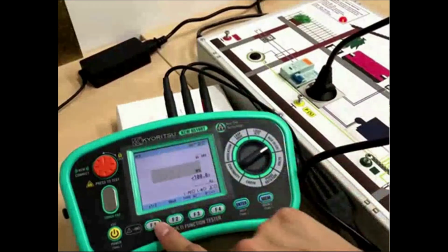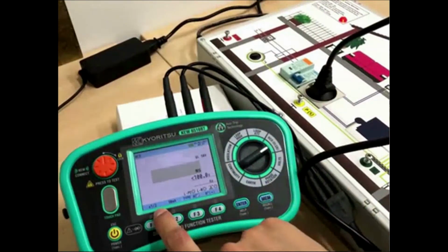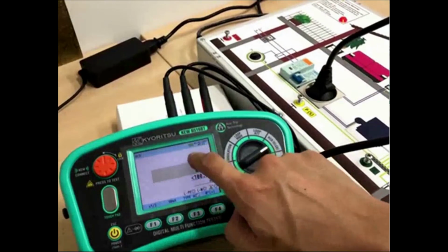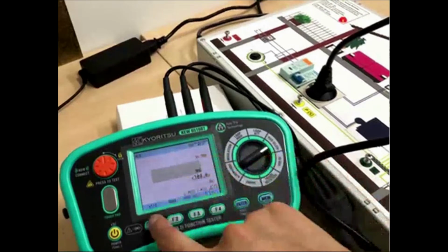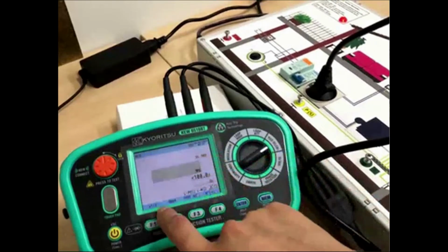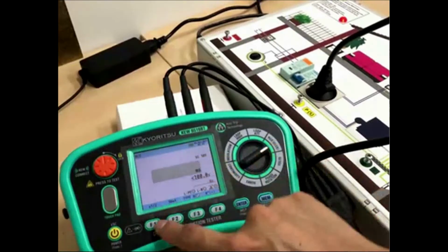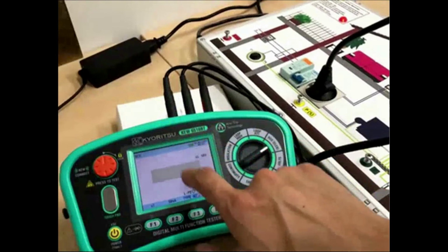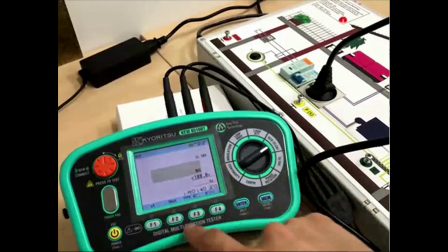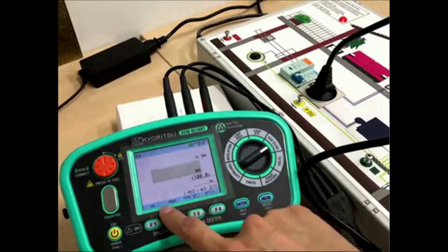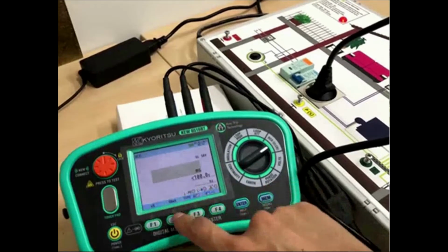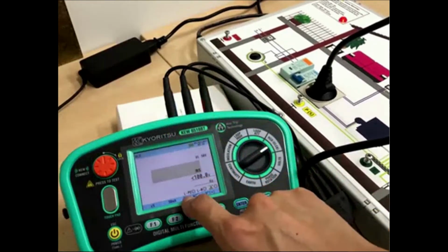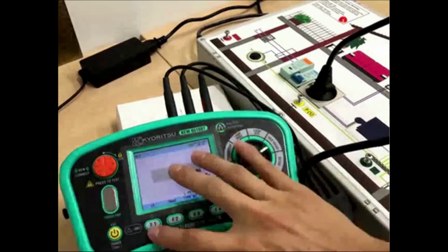Now I show you, this one is half. Half can trip or not? Half of the 30 milliamp is 15 milliamp. Just now your tripping current is 18 milliamp. So this function, if I use this function, the RCD can trip or not? Cannot. This one time 30 milliamp can trip or not? Can, because 30 milliamp is over 18 milliamp. Okay. This one 5 times more tripping. 150 milliamp output. Your tripping current is 18 milliamp. So can trip or not? Can.